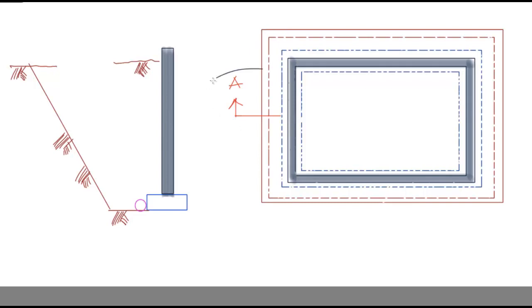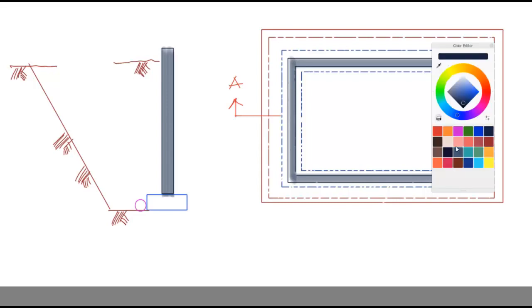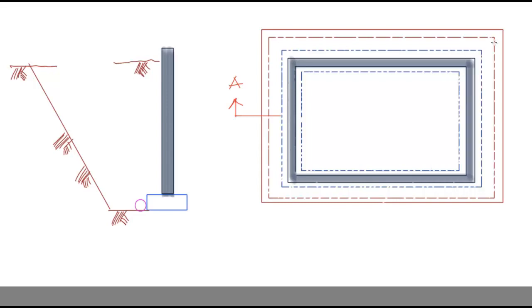So if we take a section, this will be the look of the section. We need to do the calculation for this part of the excavation, which is just called the bulk excavation, and then we also need to do the calculation for this other part of the excavation. This is called the perimeter excavation.